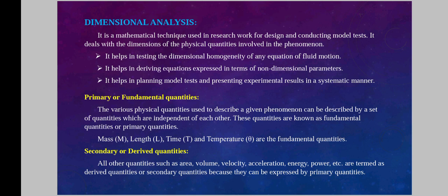It is a mathematical technique used in research work for design and conducting model tests. It deals with the dimensions of the physical quantities involved in the phenomenon. It helps in testing the dimensional homogeneity of any equation of fluid motion. It helps in deriving equations expressed in terms of dimensionless parameters. It helps in planning model tests and presenting experimental results in a systematic manner.